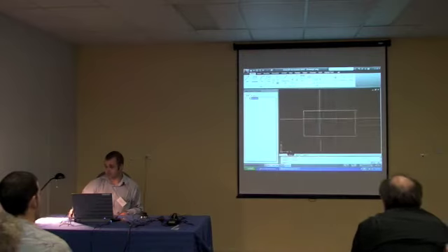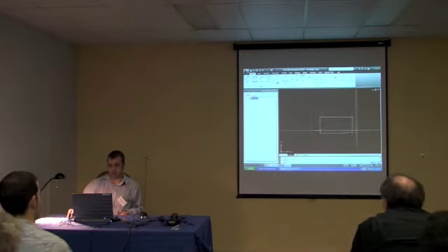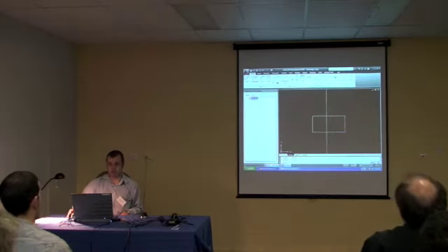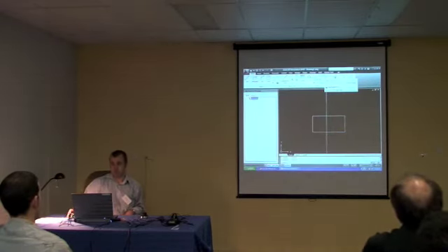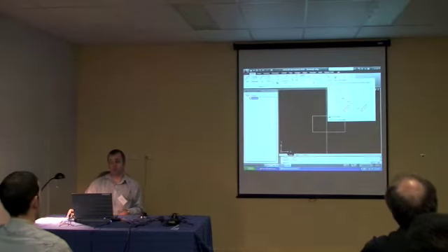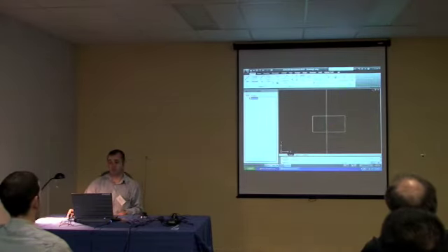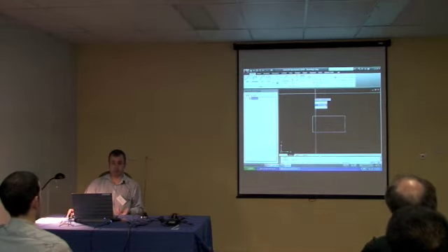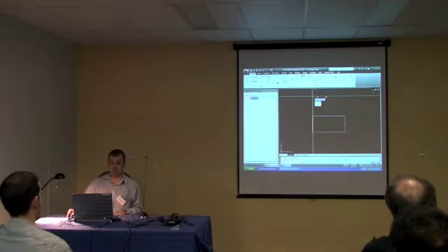It's fun. Now, once you've done that, you may want to copy and rotate it. There's the move, copy, and rotate function. If I do that, I can choose to rotate, move and rotate, or rotate and then move. Maybe I want to move it then rotate it. Do I want to copy it? Yes or no?